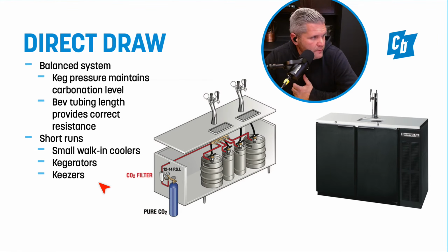But putting this all together, we've got the gas, which goes to a regulator, which feeds the gas line. This little white rectangle in here would be a gas filter, which feeds a manifold, which can take the place of a secondary regulator set. A manifold would just be a block of aluminum that's got some switches on it, so that basically you can take one feed of air and divide it into 4.